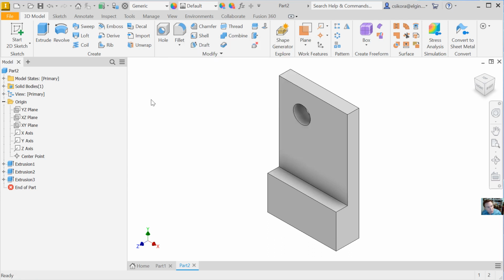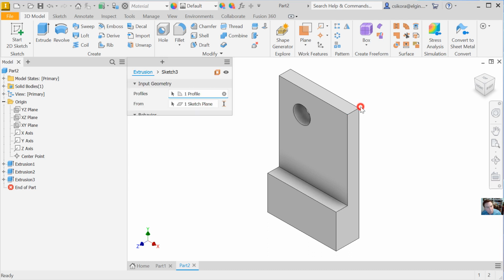There's the Fillet Tool up here. You could hit the F key, or you could literally click on an edge, and the Fillet Tool comes up automatically. So you could select this edge, and you could hold Shift, not Control, for multiple edges. Okay, now go ahead and hit Create Fillet here, or you could hit the one up top.